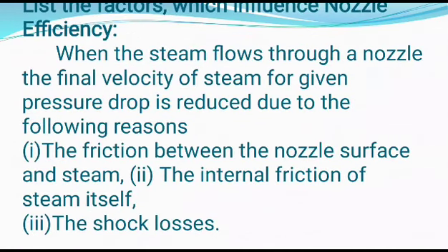List the factors that influence nozzle efficiency. There are factors affecting. First one is the friction between the nozzle surface and steam. Second is the internal friction of steam. Then third one is the shock losses.